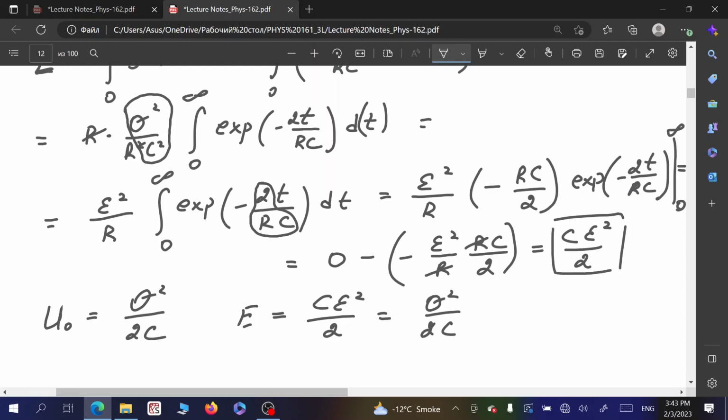That's why we will lose it. So we will lose part of the initially accumulated potential energy inside the capacitor. And eventually, when we measure total energy dissipated over the load resistor, it will be smaller than we assume was accumulated initially in the capacitor.